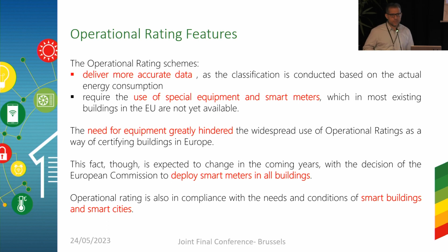What is the second element, which has been the obstacle all these years to have schemes for operational rating being developed? It is the fact that in order to measure, we need to have hardware, we need to have the equipment, we need to have the devices installed in a building that provide the information about the actual energy consumption of the building. And the need for equipment actually hindered all these years the development of the operational rating as, let's say, the major way of certifying the energy performance of buildings.